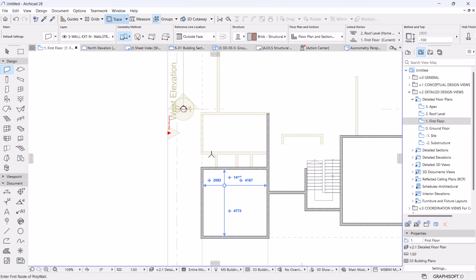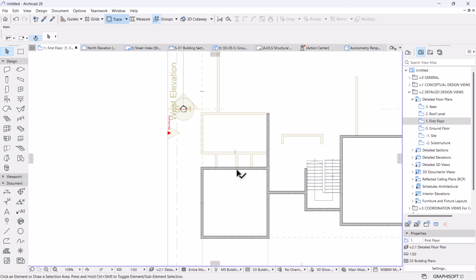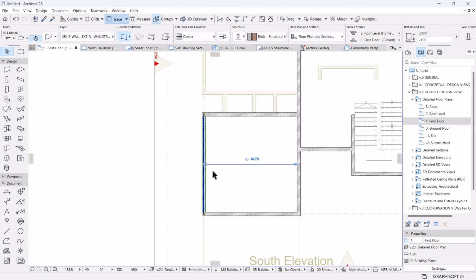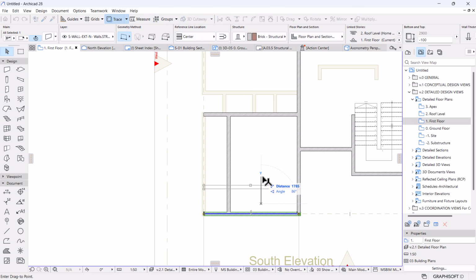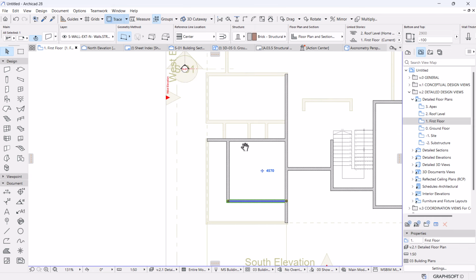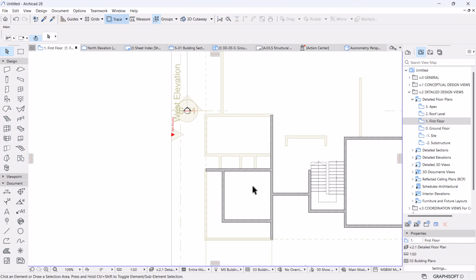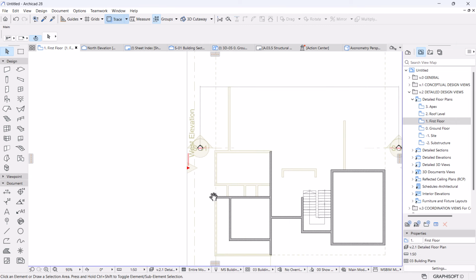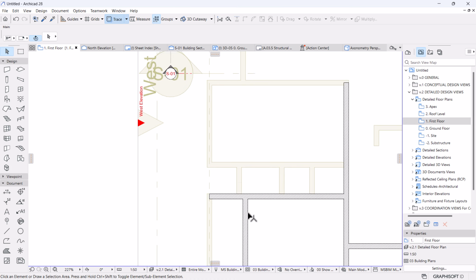So with the master wing, basically what I would want is a balcony that is around, on the side, and also in the front. So I'm going to take this wall, Control Shift, or even not Control Shift, I can just move it inside by 1.7. Do the same to this one, 1.7, and I can trim over this extents. Perfect. So this basically will be our balcony, and then this will be our pajama or the lounge for the master bedroom.